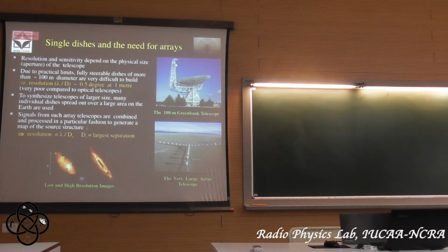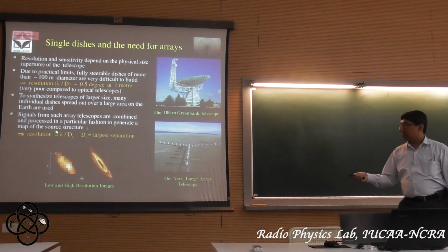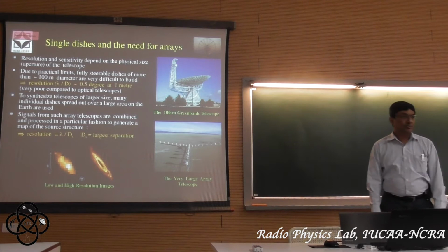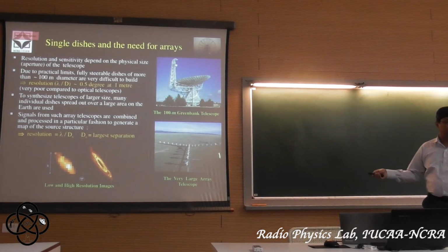But mind you, this is only as far as the resolution is concerned, right? So it will give you the resolution which is comparable to the resolution of an aperture whose size is ds, where ds is the largest separation between the antennas. Of course, it will not give you the sensitivity of an aperture of this size, because large areas of this aperture are empty, right?